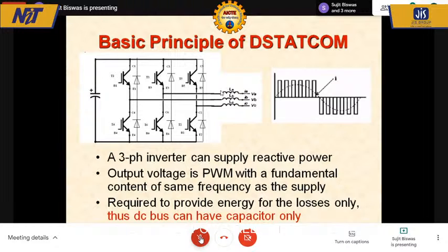But remember that you are injecting harmonic currents, because the current in this line, as I had shown earlier, is not a sine wave at all. And this can be used as a reactor or an inductor, depending on your application. And if you think the current can be filtered out by putting a capacitor, just wait for a few minutes until we see what is the effect of connecting a capacitor on this side in the presence of harmonics.